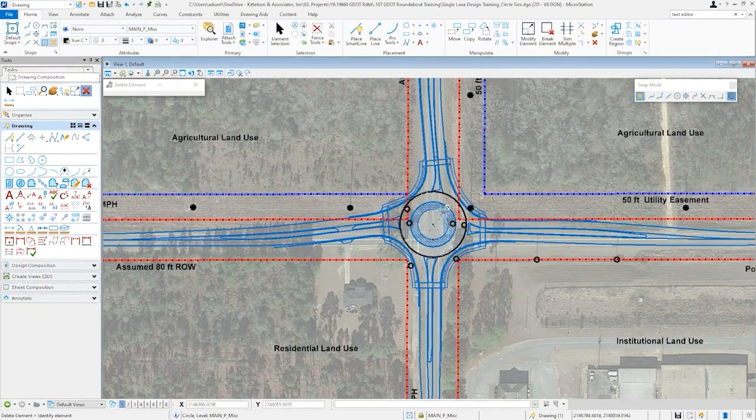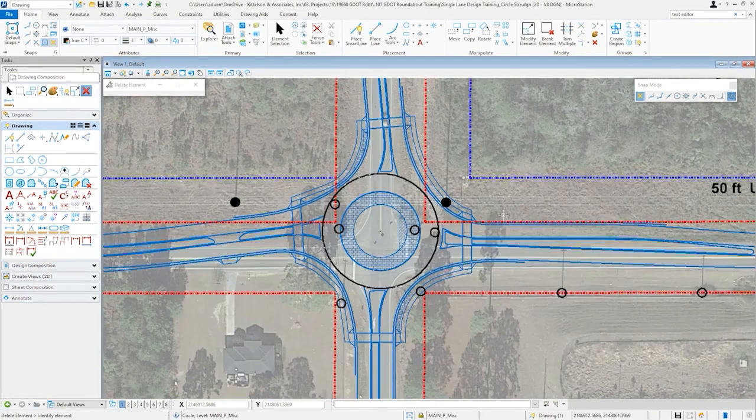Now, to accommodate the shift of the roundabout to the north, you'll notice the approach alignments on the east-west roads have also been shifted to the north. We're maintaining the chicane for speed control, but that will also result in more right-of-way impacts in the easement area along both approaches. So in addition to the right-of-way impacts in the corners, we're also chasing right-of-way impacts down the 2 approaches.